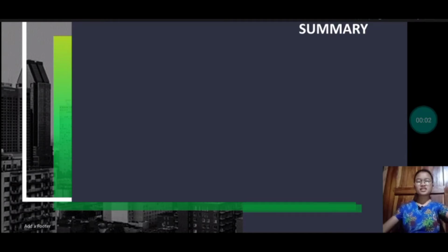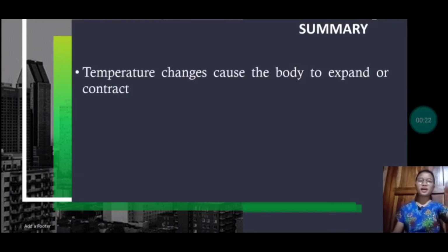Before we end this lecture video, let's have a quick summary and few add-ups. We all know that thermal strains are strains that develop when a material is heated or cooled. This means that this happens when there is a rapid increase or decrease in temperature, which then causes the body to expand or contract. So if temperature deformation is permitted to occur freely, no load or stress will be induced in the structure. In some cases where temperature deformation is not permitted, an internal stress is created, which is also known as thermal stress.